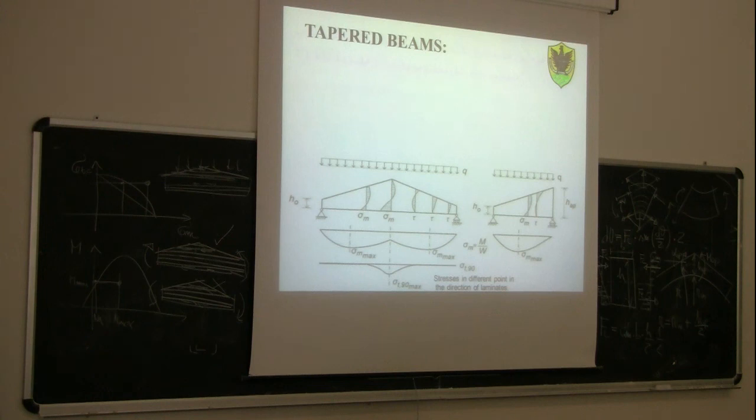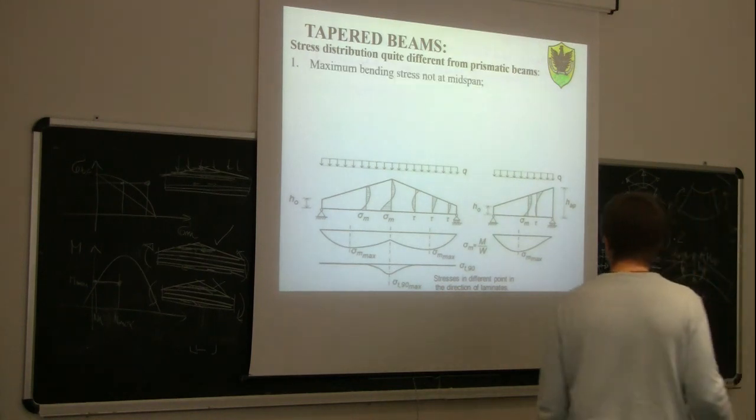So, in general, in terms of taper beams, it's very important to realize that in this kind of beams, double taper beams or single taper beams, the stress distribution is quite different from prismatic beams, the ones that we know better from, of course, mechanics of materials.